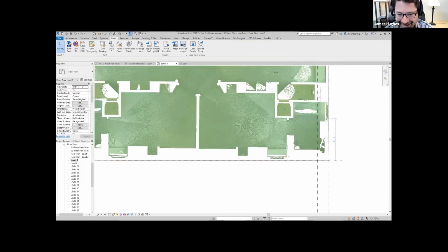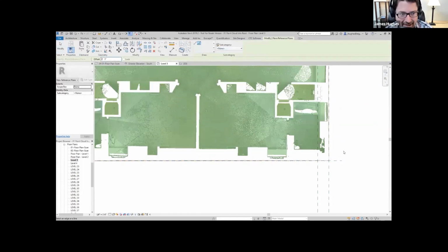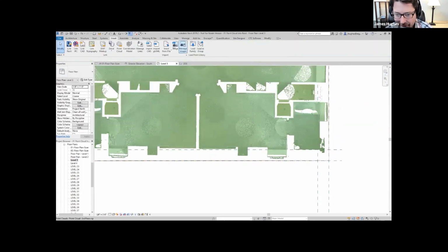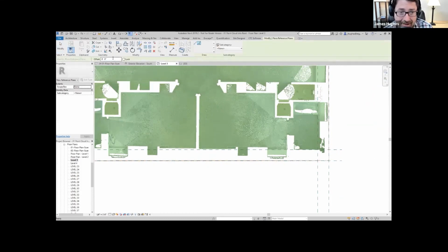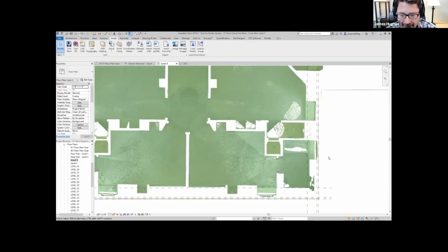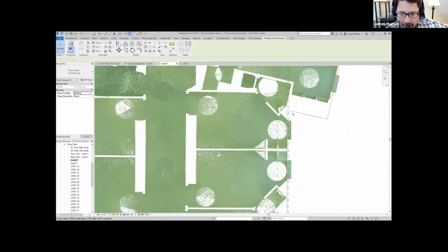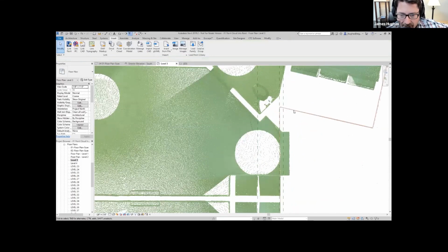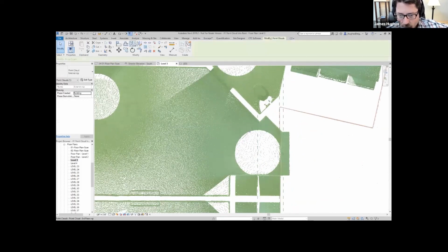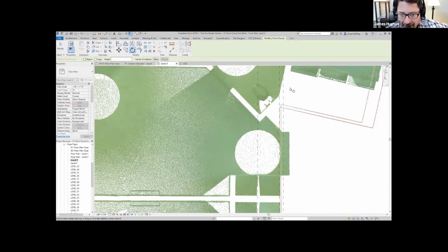I'm not this fast. All right, so I stretch them so that they definitely intersect past one another. I like to name them sometimes. And then I set a 4-inch inset because we've got limestone that actually steps in at the windows that you'll see here in just a minute a little bit more clearly, not so much on the 3rd floor. But to check or fine tune my rotation, I can see that that outer needs to rotate about 4 inches over a distance of about 400 feet.